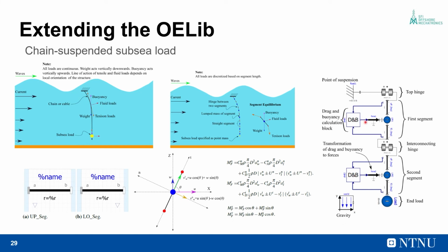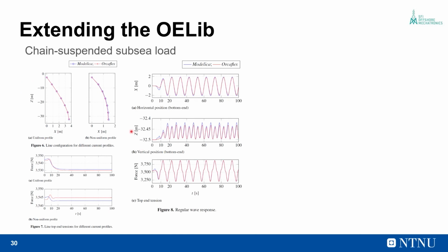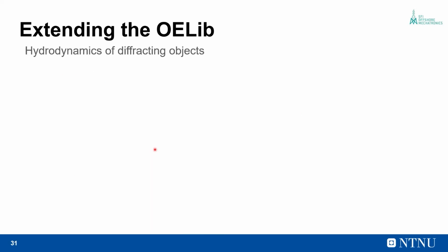And we make use of drag and buoyancy blocks, inside which we use the Morison equation to calculate the fluid loads. And it's seen that the results using this method are more in agreement with the OrcaFlex results. And the Modelica code is available for reference, and the download location is given in this paper.